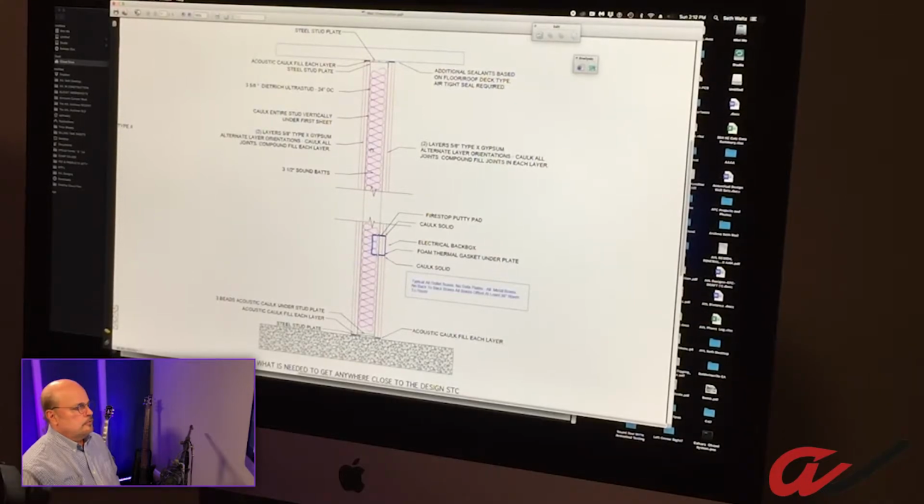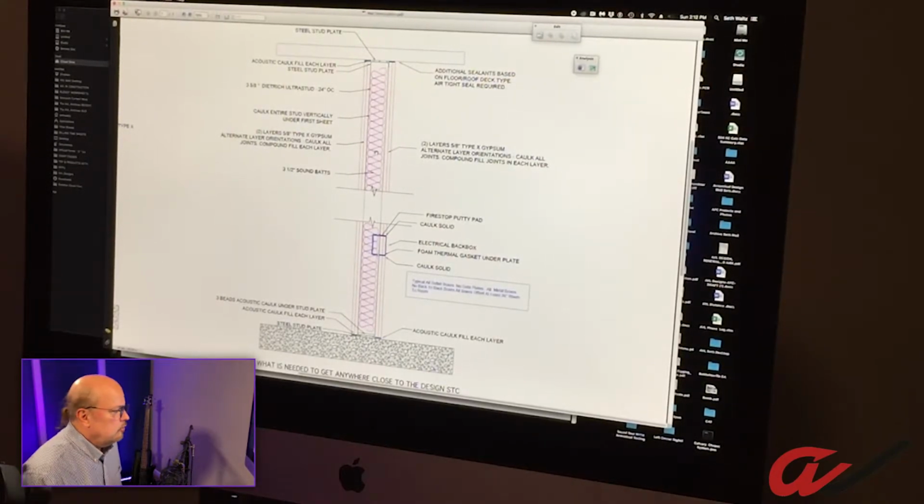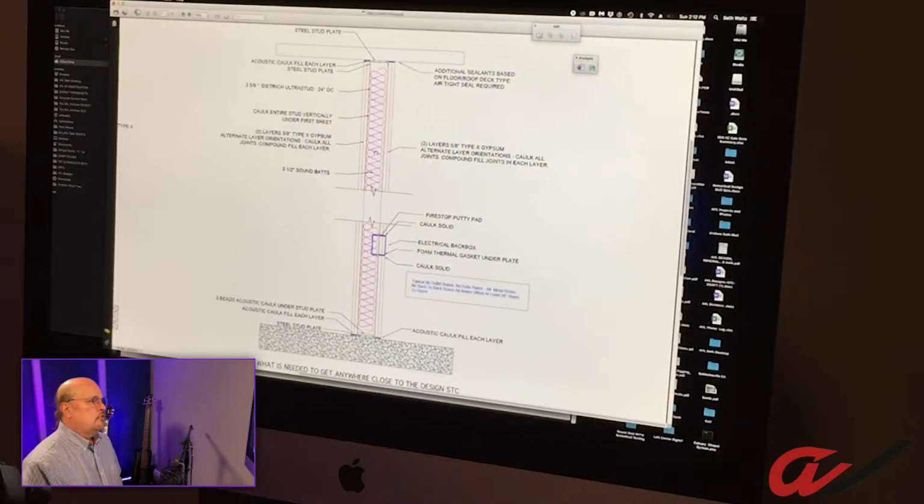But there's a huge difference between mineral wool and rock wool. So you've got to be sure you're actually getting rock wool, and that the mineral wools that are out there, there's all sorts of configurations. They're considerably different. Some of them have settling problems. Some of them don't have quite the same acoustic value. But when you get into looking at the actual acoustic value of the product tested by itself, Rockwool has significant advantages at low frequencies and significant advantages overall. Whether it justifies the cost depends on your application.